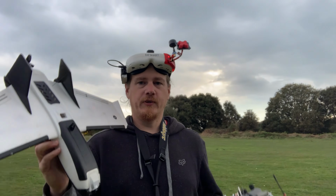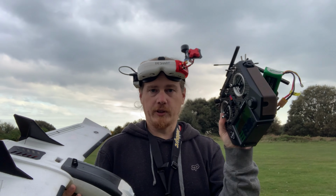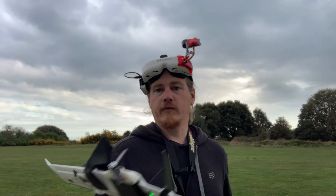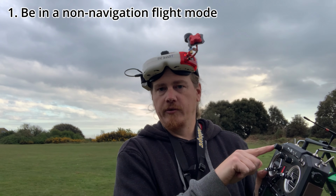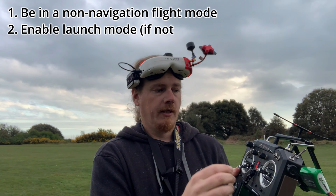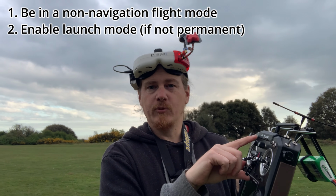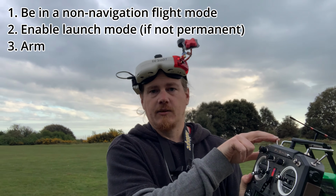Right, so we're at the field. Everything's set up, we've got our satellites, everything's plugged in, so we'll go through the procedure for the auto launch and then I'll head over there and chuck it. The first thing I want to do, as I said, is make sure that we're in a non-navigation flight mode. So I'm in manual at the moment. The next thing that we'll do is enable auto launch. If you've got it permanently enabled, you don't need to do this, so launch mode enabled. Next, we will arm.